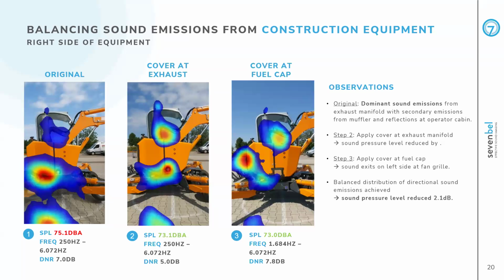An acoustic camera per se cannot be considered like a sound pressure level meter, which has a class 1 or class 2 accuracy. But what we can say, and this at least holds for our equipment and our technology, is that it is comparable to class 2 measurements. What we typically recommend is that you have, of course, a dedicated sound pressure level meter to perform your regulatory measurements with a calibrated device, and that the acoustic camera is an additional measurement instrument that you use for troubleshooting, for trying to find out what the root cause is, and for effectively validating your technical solutions.